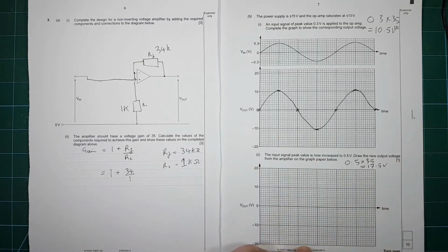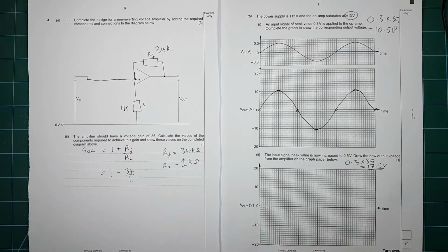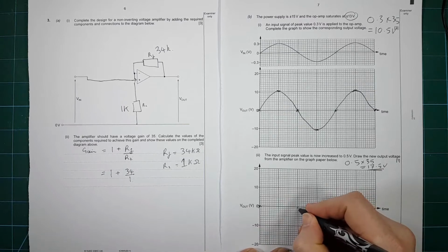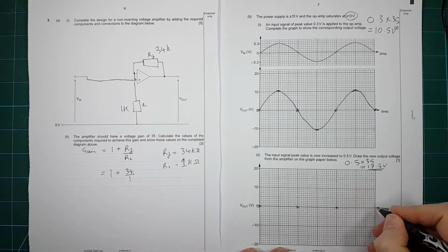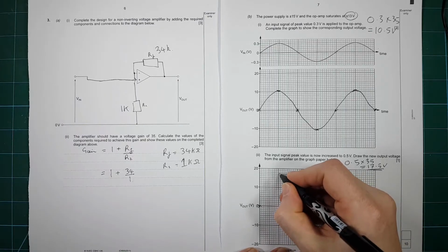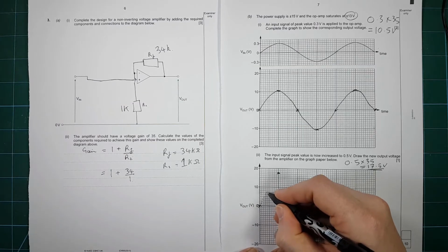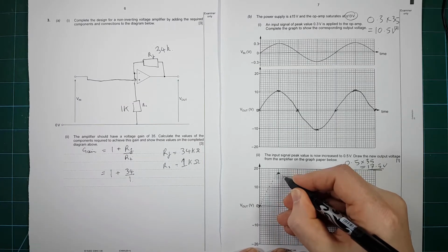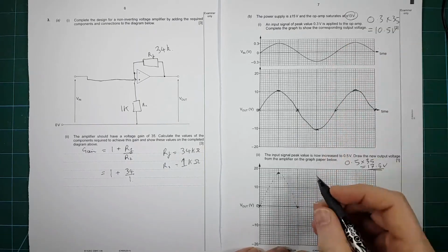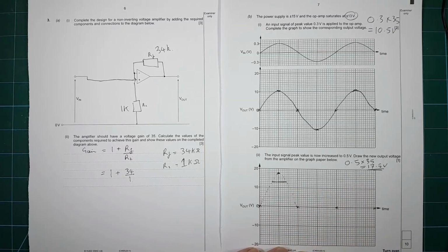Right. Now we've got to notice that 17.5 is above the saturation voltage of 13 volts. So we're going to start at naught again. We go through the noughts here, here, here, and here. And we're going to aim for 17.5, which is here. So I'm just going to draw a dotted line to start with of what it's going to look like. But it doesn't look like that because it can only get as high as 13 volts. So the maximum it reaches is there.